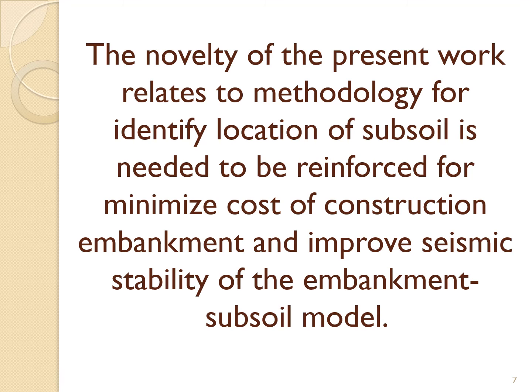In this investigation, the size of the geogrid sheet was 5 meters, and each geogrid element has 2 meter distance, and the geogrid is in only one direction. It can be in different directions, different geometry.